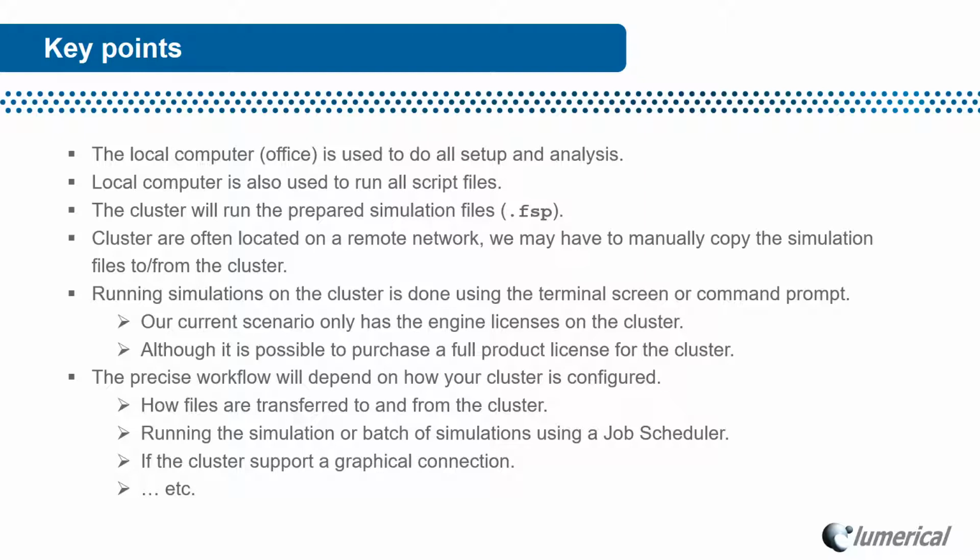Next, the cluster is often located on a remote network, making it necessary for you to manually copy the files to and from the cluster. Similarly, it is usually necessary to start the simulations from a non-graphical terminal, since the cluster does not have a license for the graphical CAD. Of course, you could consider purchasing a full license for the cluster, but that's not the configuration we're looking at here.